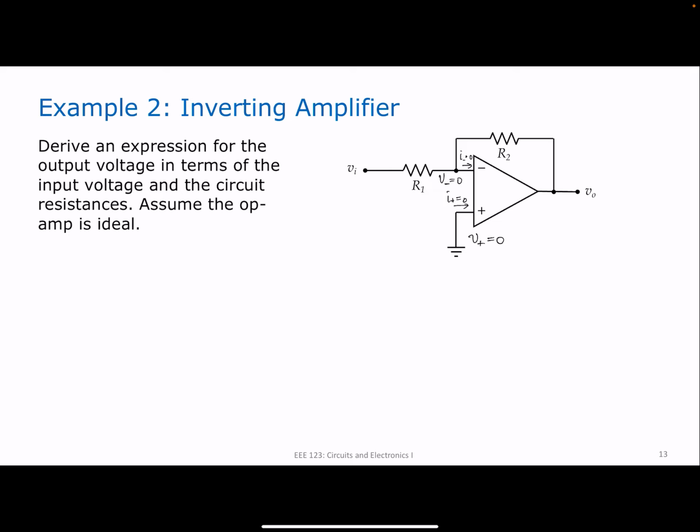Okay. So having said that, what is the next step? The next step is we apply our known circuit analysis techniques to get a relationship between V of O and V of I. So let's do a KCL, do a nodal analysis or KCL at your inverting terminal.